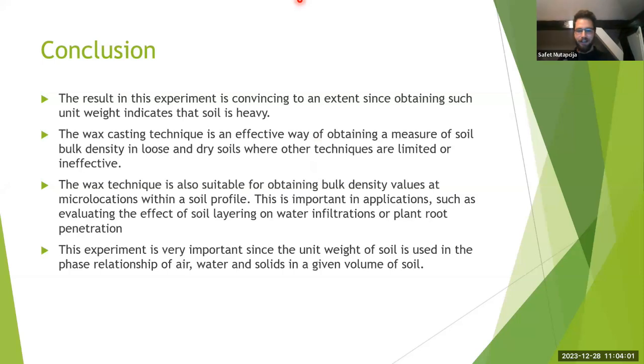Usually, if it is clayey soil or silty soil, really fine-grained soil, or even sand, when you put water inside of your sample, the properties of your soil are going to change. There are some states of the soil that you have: solid, semi-plastic, plastic, and liquid. Of course, if it's super dry, it acts as a rock. That's just pure solid. But if you increase water, the soil is going to start behaving completely plastic.